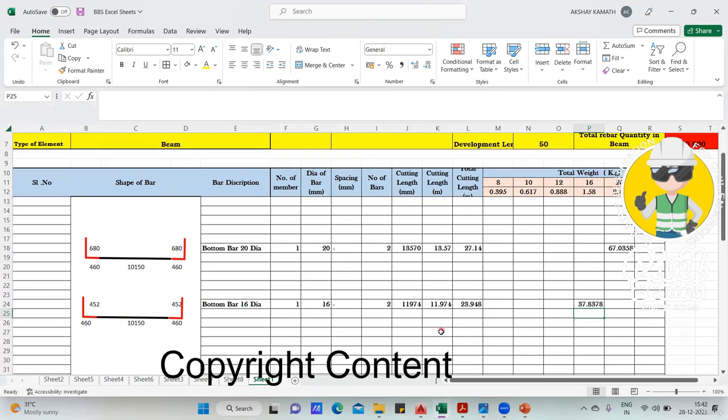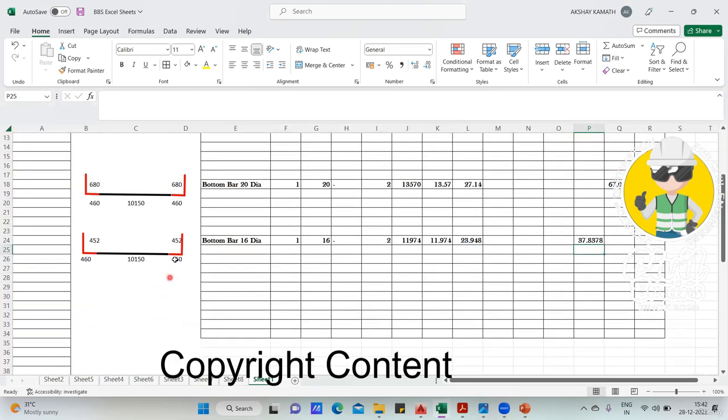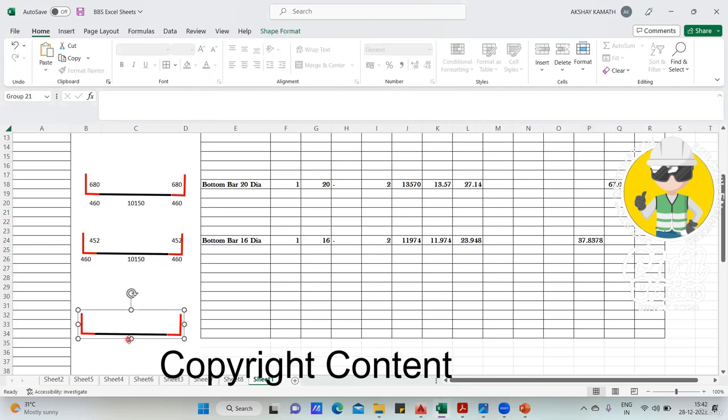Now, again, I feel the rest of the things you can do on your own. I explained this, it was too complicated. Other than that, if you want to do the top steel, Control C, Control V, bring it to the bottom and just click here and make it like this. Finish. Your top bar is ready.